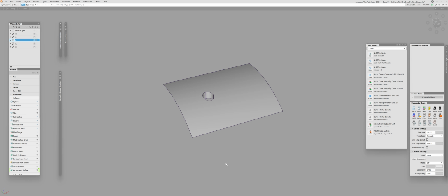Right. So as a conclusion, all your NURBS data, everything you see represented in a viewport, is a mesh through the tessellation process. Tessellation defines how your NURBS geometry will be presented, and all visual issues you have in your models are tessellation related. The best way to tessellate your NURBS data is to use external tessellators instead of built-in ones, at least at the time of recording. And the tool I suggest is Pixyz. It is expensive, but it delivers. That's it. Thank you very much for watching, and I will see you in the next one.